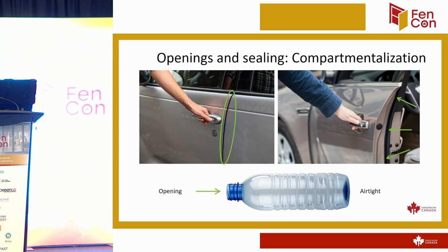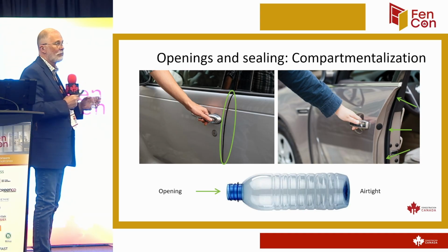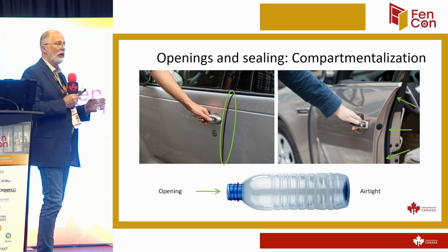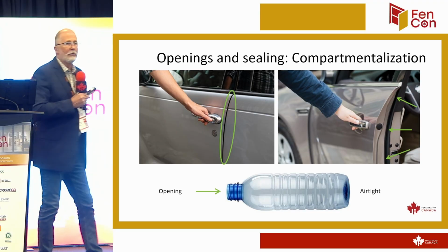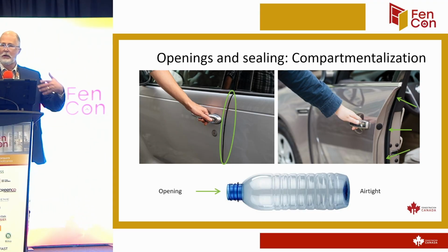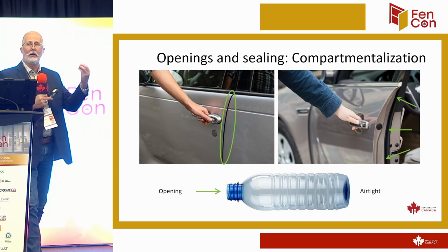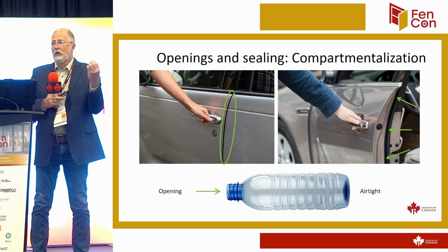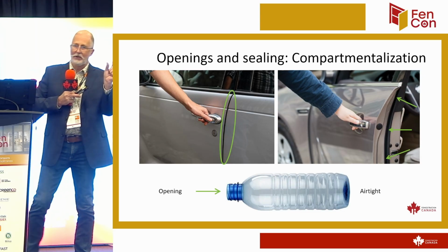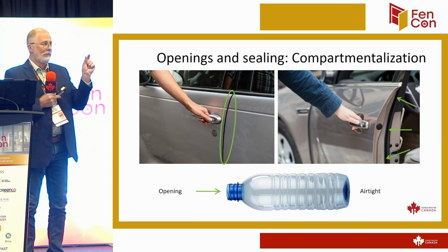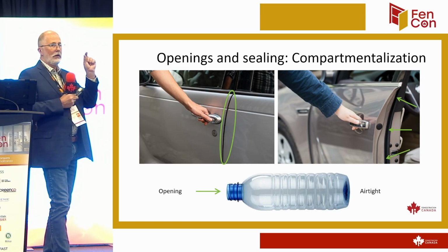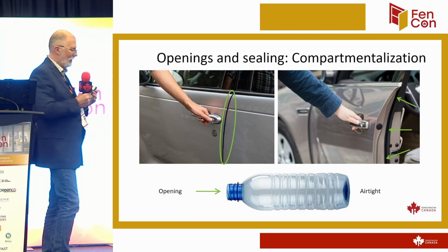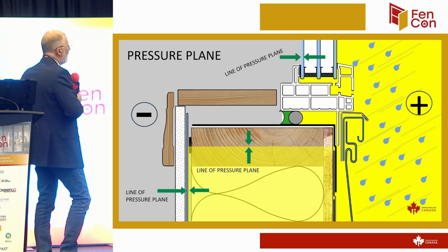It's very low. So that principle alone teaches us that compartmentalization or partial compartmentalization keeps the water from flowing into those cavities, which is what we want to look at when we look at a window. We just want to think about, how do I reduce the volume of water getting in there? And that's what rain screen principles are based on. It's not pressure equalization as much as it is pressure moderation. Equalization is very difficult to do, very challenging. But moderation, you just need a higher pressure on one side than the other, and it performs really well. So there's the principle behind the rough opening.